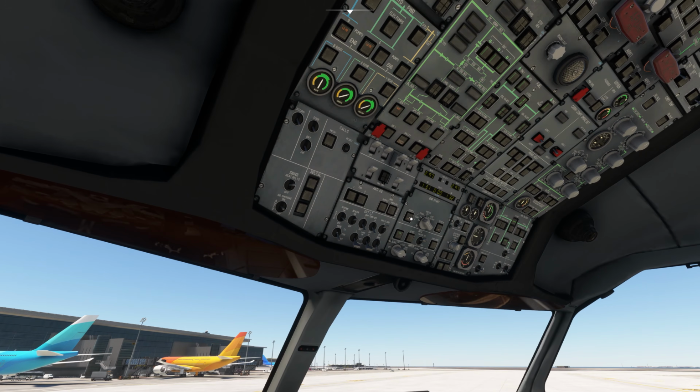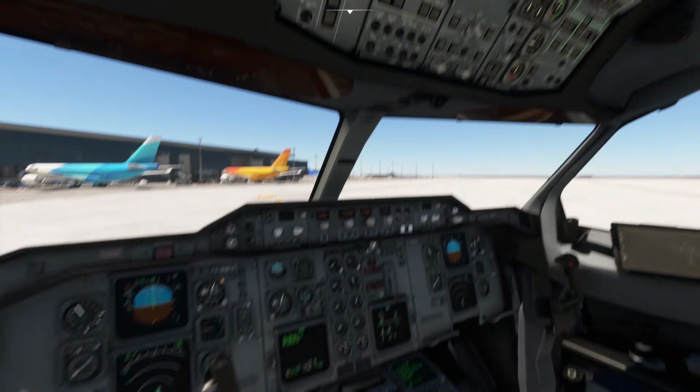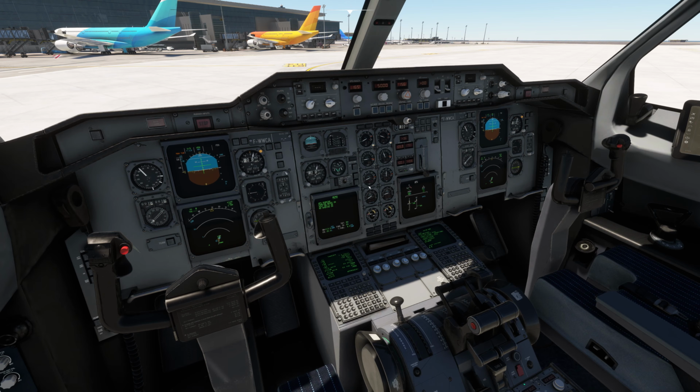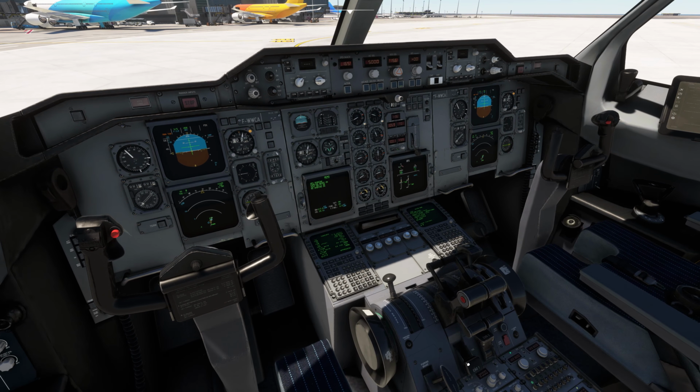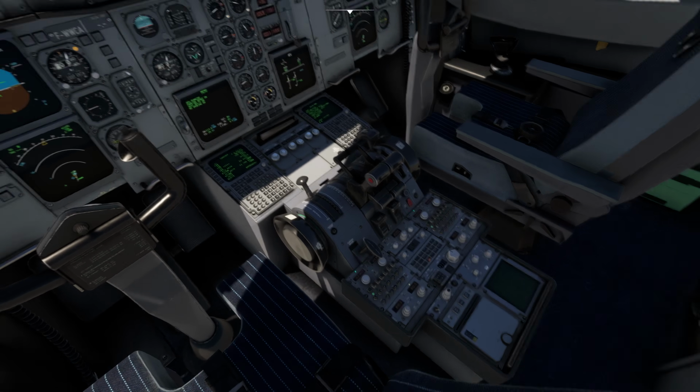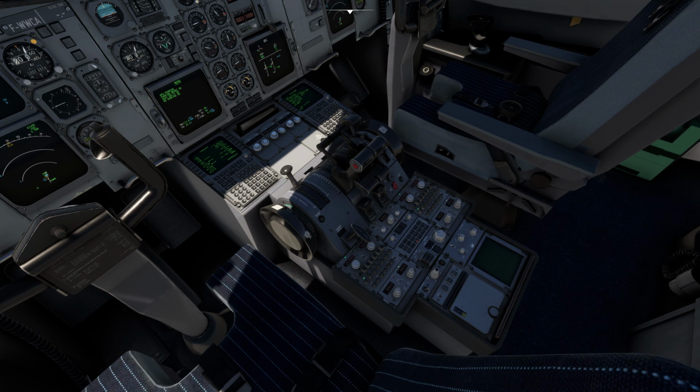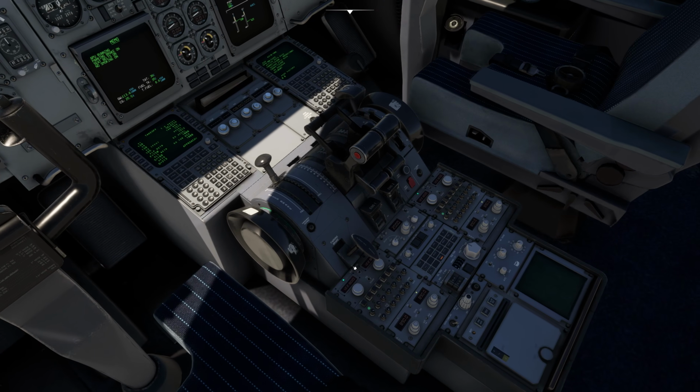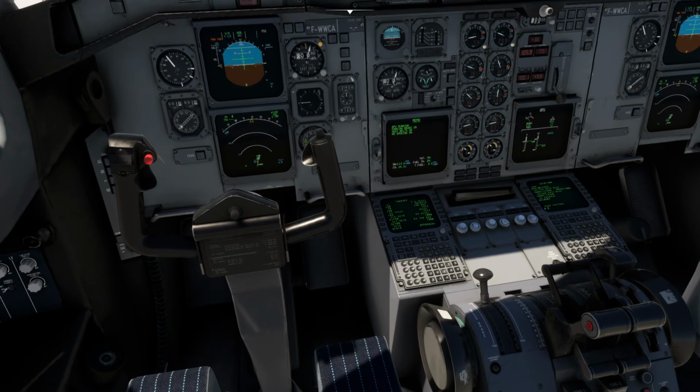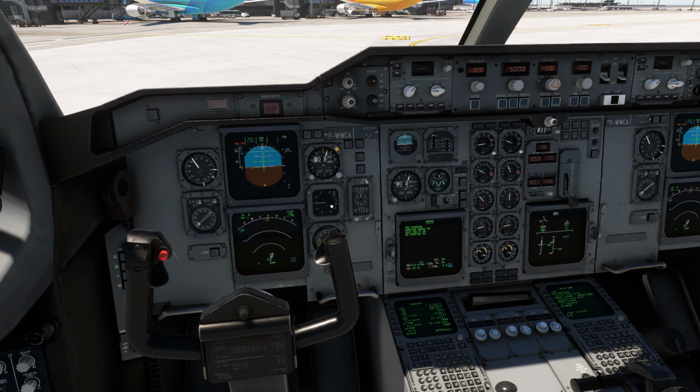Now it's time to turn on engine 1 as well. Just press this button. It says open and wait for this N2 for engine 1 to reach 20, and then you can turn on the fuel control switch for engine 1. And here you go. That's it. And then you have the weather radar. Just turn it on. You have the traffic avoidance system and collision avoidance system, TRA. Just set it to TRA. You will see traffic over here if there is any traffic.